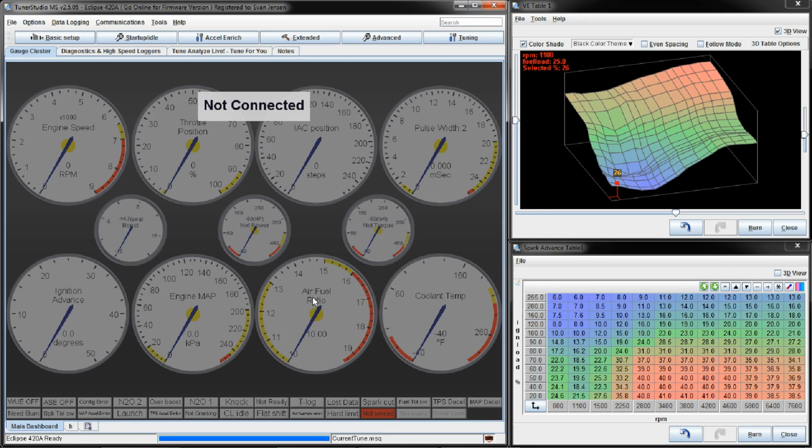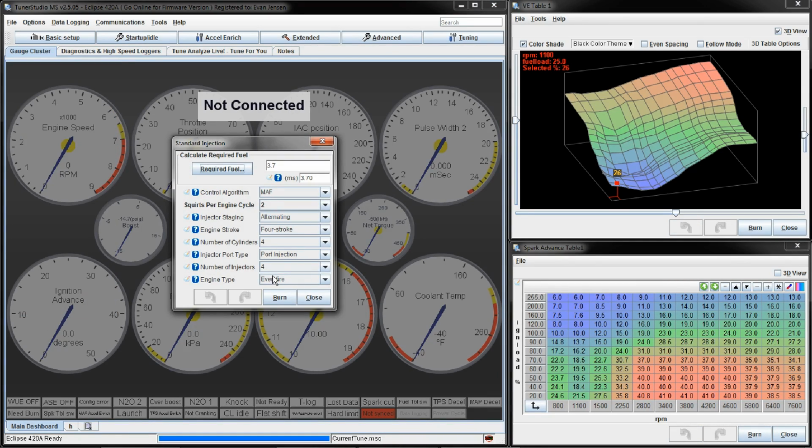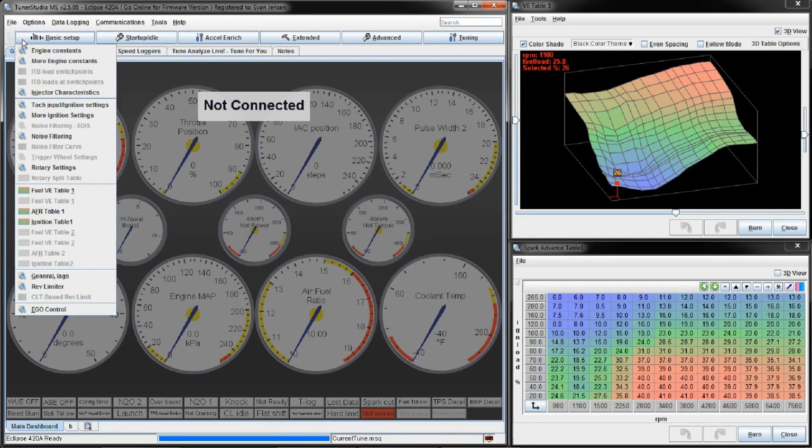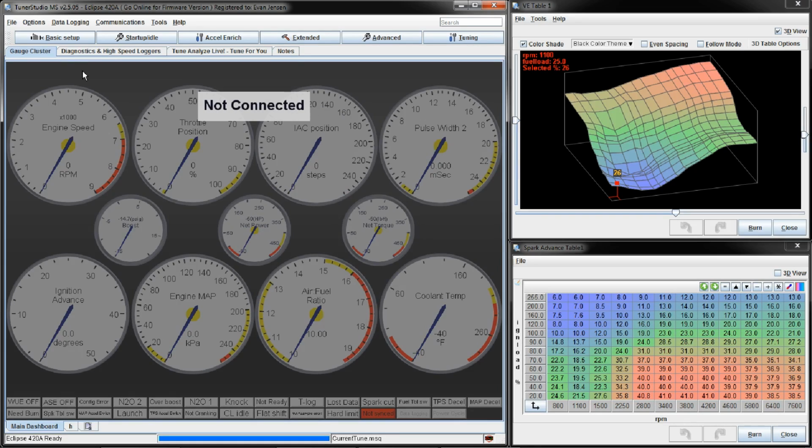I pretty much copied those values, but they do make sense. And keep in mind here, back to that same screen, Megasquirt doesn't know what sort of engine you have, so you have to tell it. It can run a 1-cylinder, a 4 or a 6 or probably a 7 or a 5, or up to a 12, I think, officially, and I think other people have run 16s and so on.